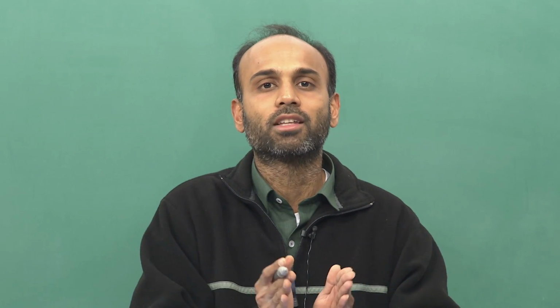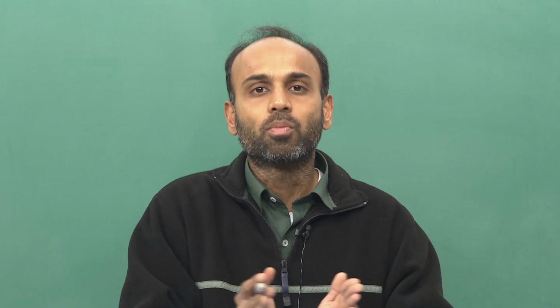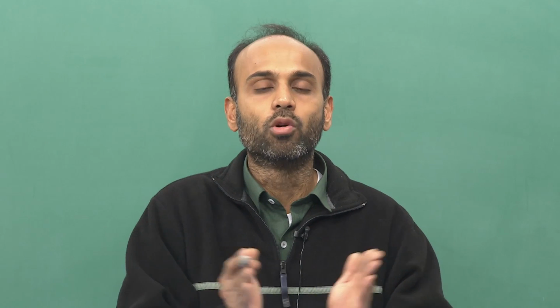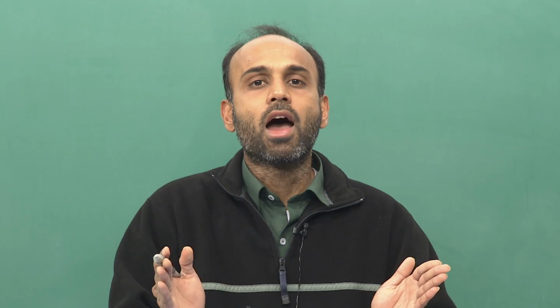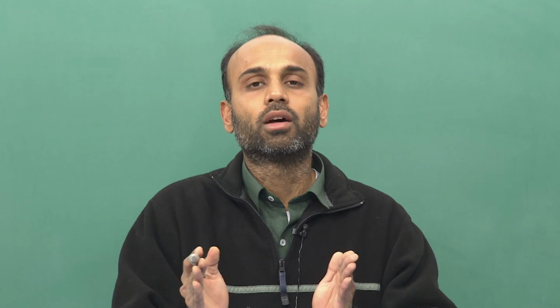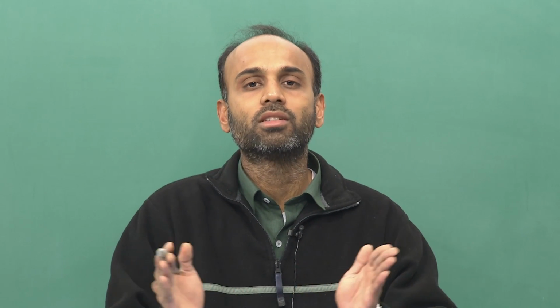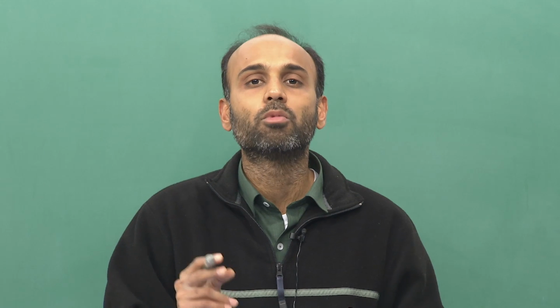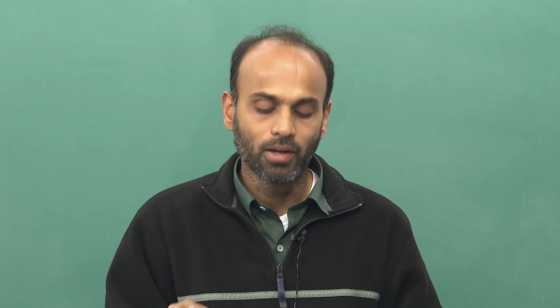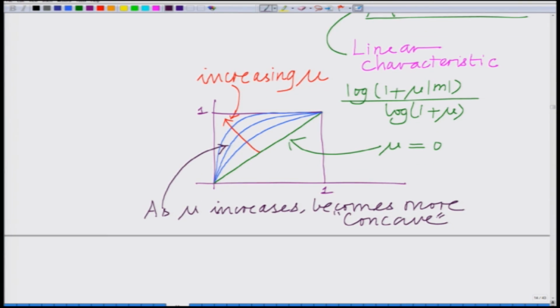So, the resolution, that is the number of bits or the number of intervals, for the smaller amplitudes or the finer amplitudes improves progressively as mu increases, and the resolution or the accuracy of the larger amplitude region progressively shrinks as mu increases. Okay. So, that is the mu law compressor.